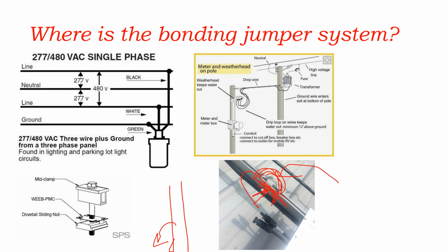And there are certain rules on if the metal is large enough, then it doesn't need to be listed. But it might be that the metal pile is so small or that it has an anodized coating on it, so it just doesn't get the resistance that it needs to actually be a ground path. So you should not assume that things are grounded simply because you have a metal on metal connection. It may not be grounded enough is the issue.